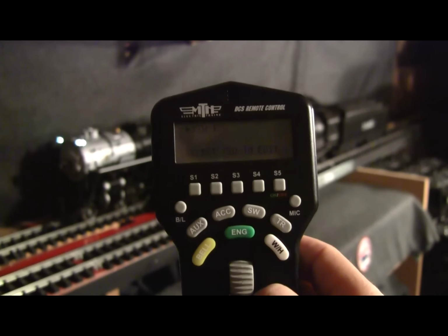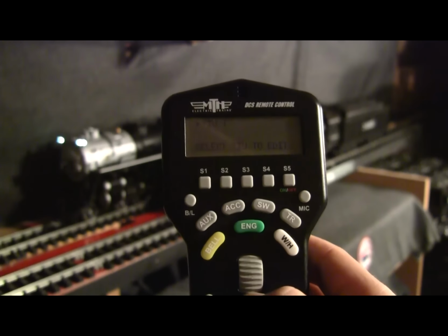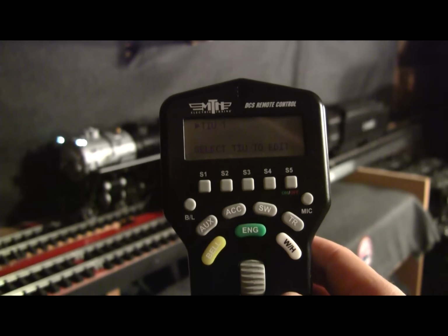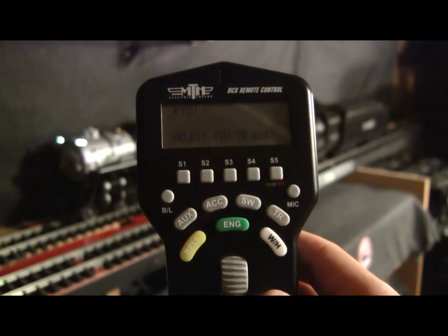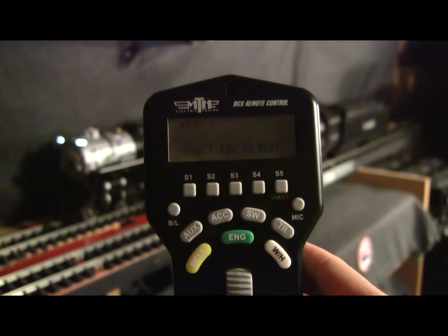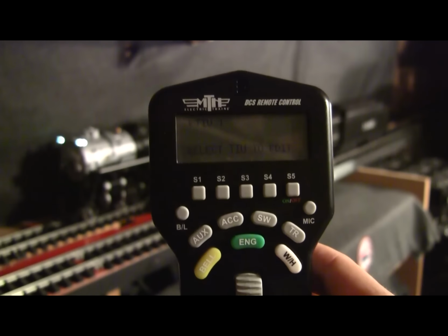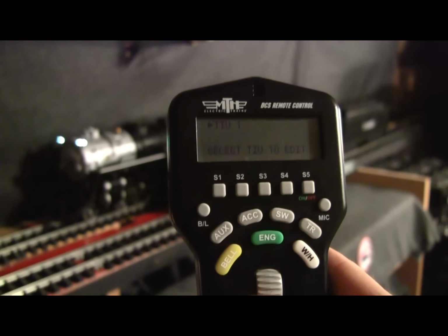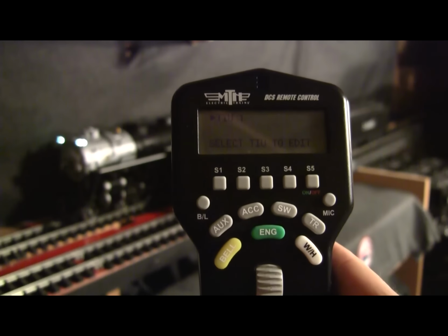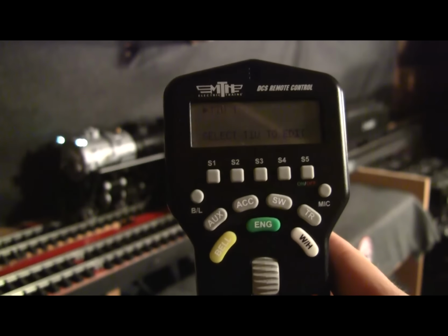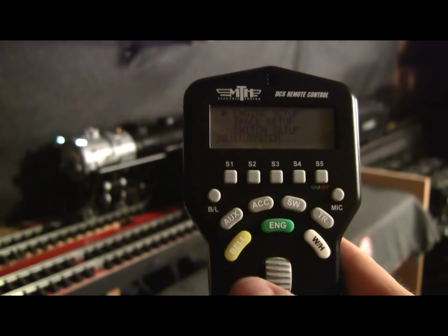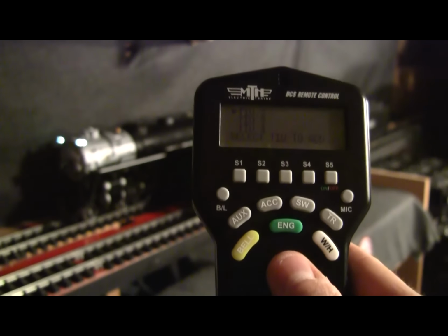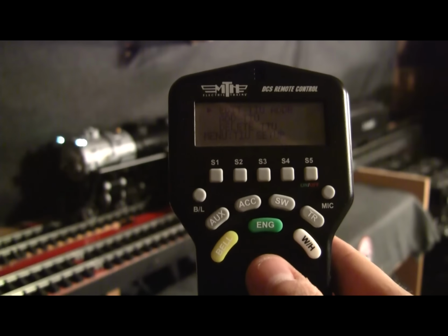When you buy a brand new TIU and remote, the remote comes with a TIU number 1 listed. In fact, if you do a full reset on the remote, it goes back to a factory default of having TIU 1 there. Same thing with the TIU. If you do a reset on the TIU address, regardless of what it was set to before, it is set back to TIU number 1. You can have a total of 5 TIUs entered in here. In fact, that's something that I can do right here. I can add one real quick, assuming that I have a second TIU added.